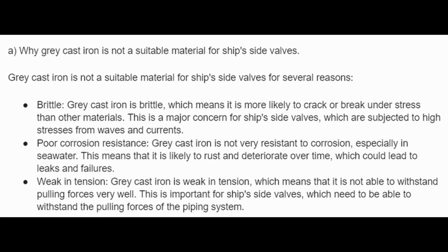It is brittle. Grey cast iron is brittle, which means it is more likely to crack or break under stress than other materials. This is a major concern for ship side valves, which are subjected to high stresses from waves and currents. It has poor corrosion resistance. Grey cast iron is not very resistant to corrosion, especially in seawater. This means that it is likely to rust and deteriorate over time, which could lead to leaks and failures.